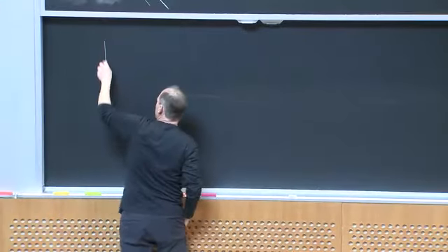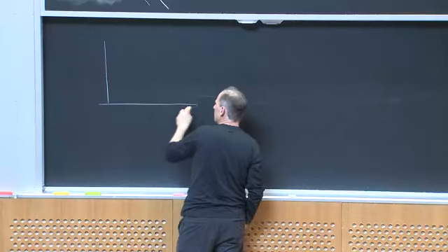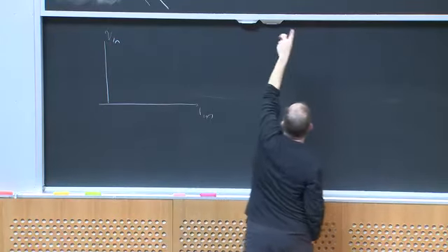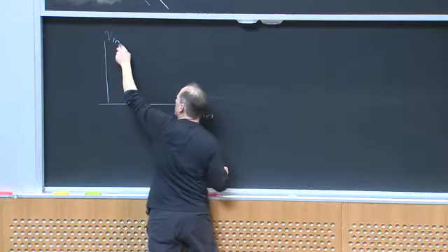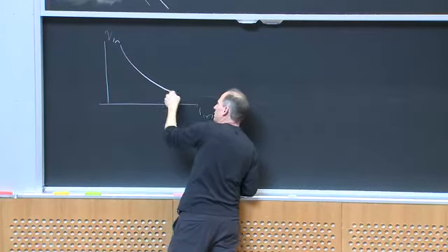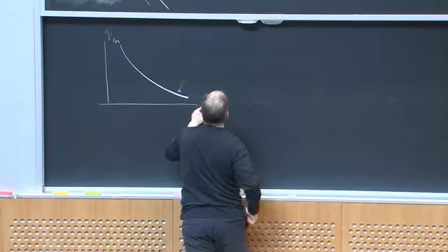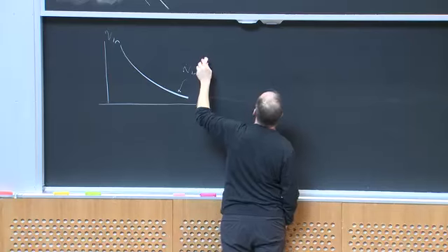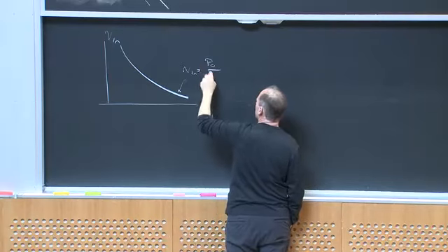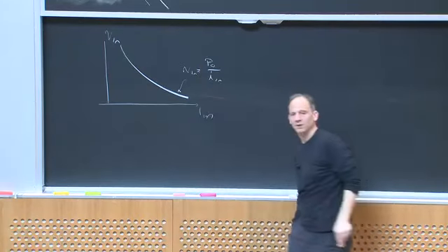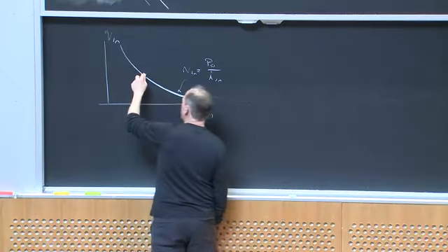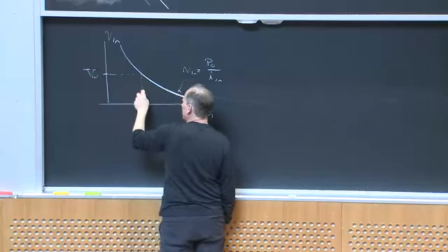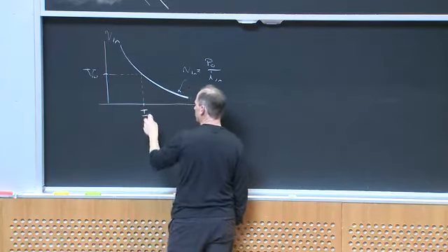What we're going to get is, here's VN, here's IN. This converter, his job at his input port is basically to maintain the system on this curve, right? Where VN is equal to P out over IN. Okay? And if he's going to sit at some operating point, maybe that's here. Maybe I have some DC operating point VN and capital IN that we're going to sit at, right?